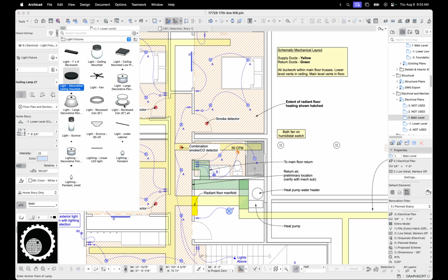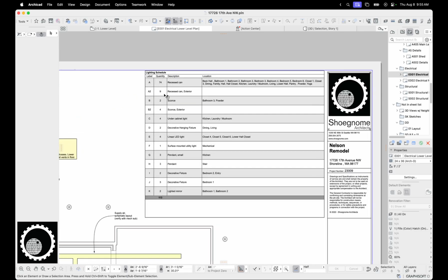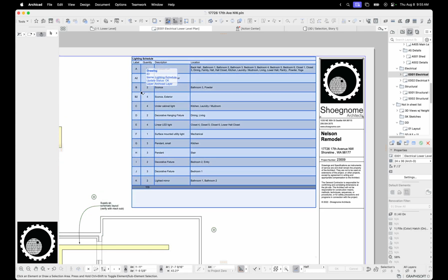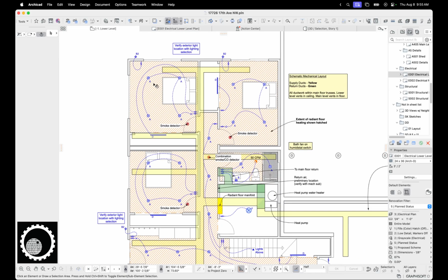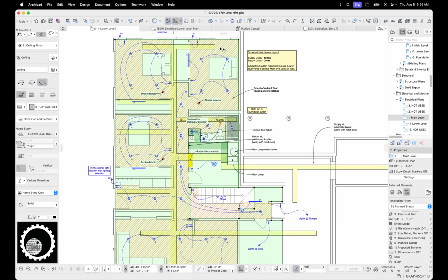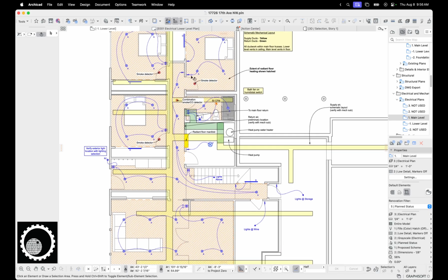The idea here is not only is your favorite set up, okay, this is a can, but if we go back to the electrical plan and we see the lighting schedule, all these A, B, C, D, E, F, G, whatever, that's all set up in the favorite. It's uniform across projects. So you're not having to spend time thinking about what tag my can should be. It's an A. What tag should my exterior sconce be? It's a B2, right? That's all just set up. It means you have more time to figure out one-off things like how to show radiant floor heat,